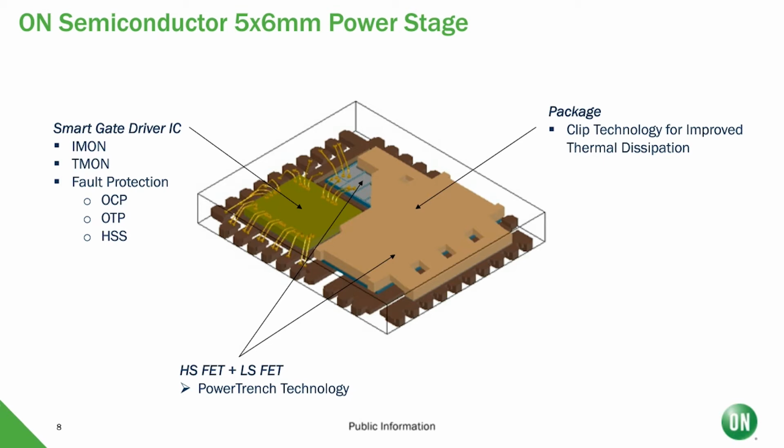But internally, the power stage itself also has internal overcurrent protection, over temperature protection, and also high side short protection. These will act as a secondary protection level on top of what the controller defines, basically to prevent catastrophic events.